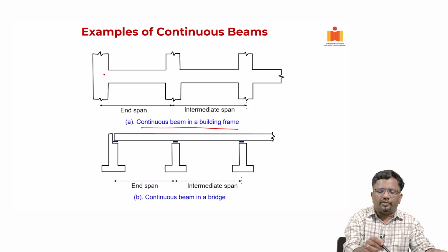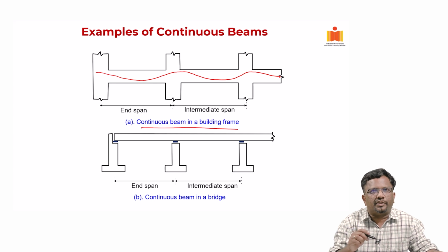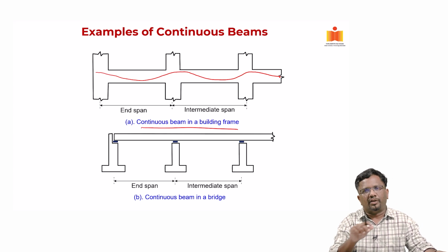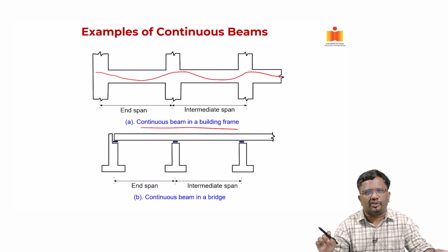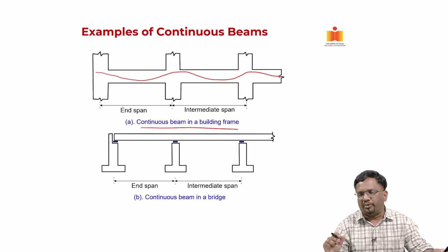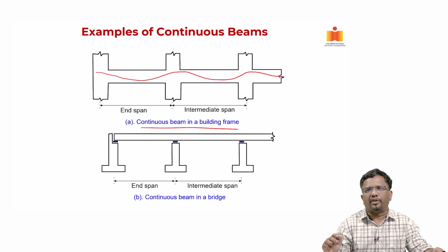Typically, you have cables that will be run in this way, right. So, you have a cable like this and goes into the support, goes like this and then goes up, and then it will be fixed like this, right. Similarly, you can also have in a bridge system, the deck, or the superstructure, made a continuous system. Every 3 or 4 spans you will have an expansion joint. So, and then you can design. So, with a continuous system we can design a more effective and economical design. So, that is the advantage of continuous systems.